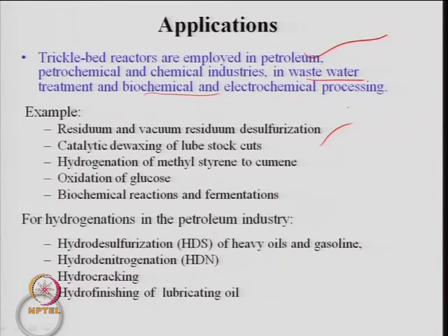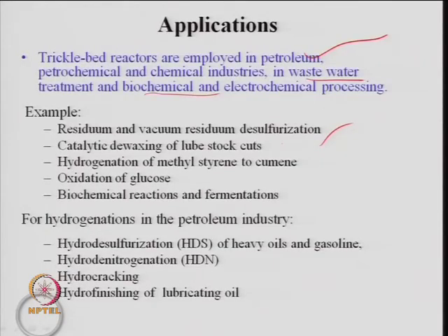Generally it is hydrodewaxing of these compounds, and cracking followed by dewaxing. So, basically the larger range of paraffin hydrocarbons are to be removed, because these paraffins are wax compounds, and in cold countries, especially when the temperature is low, these may solidify. So, we need to remove these higher molecular weight paraffin hydrocarbons. Hydroisomerization is one way by which it is cracked and isomerized to get a gasoline range hydrocarbon. So, these kinds of treatments can be done, again in the category of hydrotreatment.